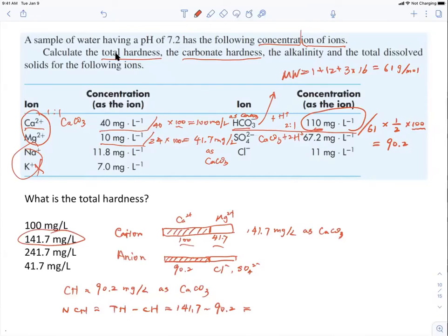So the reason why we do that is because once we know which one belongs to which, we can come up with different methods to remove the hardness. We can raise the temperature of the water, or we can put in the lime and soda, right, to basically form sedimentations for these hardness ions.